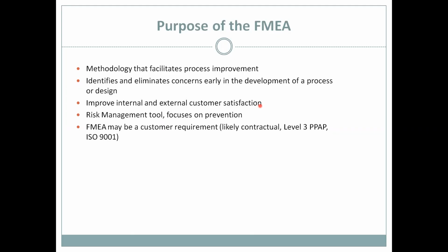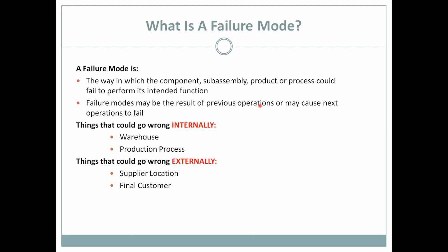Sir, in the control plan, first of all we define the PFD, the process flow diagram. Then we prepare the FMEA, where the occurrences happen at that particular stage. We detect or identify them at that stage, and decide which action we will take on that occurrence. Just identifying that in the FMEA, and then we will prepare the control plan.